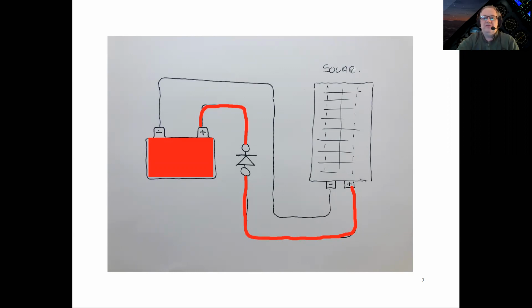And in the absence of light, so when it gets dark out and this solar panel no longer has light falling on it, producing the voltage, interesting fact, what happens is the current without this diode, the current from your battery source here will actually feed the opposite way back into the solar collector.